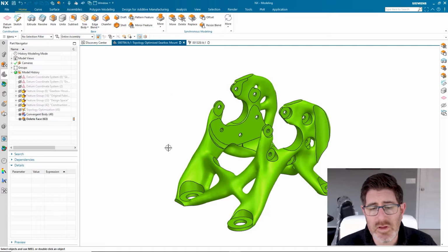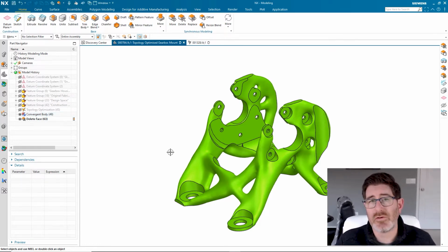First thing I'm going to do is take these holes down here at the bottom that are pretty large, and I'm going to shrink them a bit, give them just a little bit more meat so that when Joe comes along with his machining process later and drills those out, he has enough material to work with to drill it out and get the exact surfaces we need.